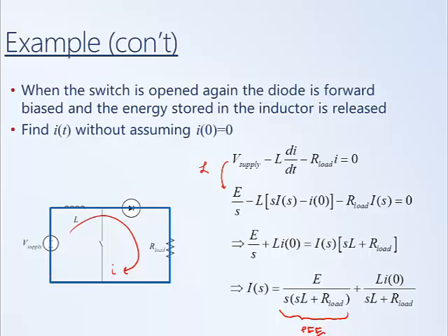Looking at this, we basically have two terms in the denominator, just S, a pole of 0, and then we have a non-zero pole. So we have two poles that are distinct and real. And if you think back to the three different cases, think about which case this applies to, case 1, case 2, or case 3. Since this example rational function has two distinct poles that are real, the coefficients, or the residues, in the numerators will just be simple constants.